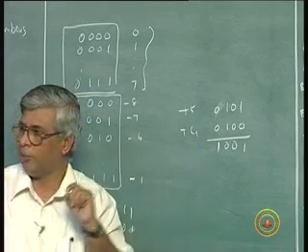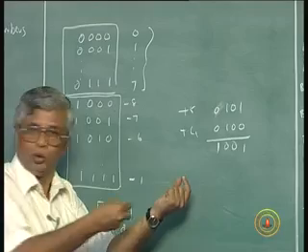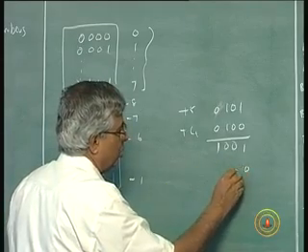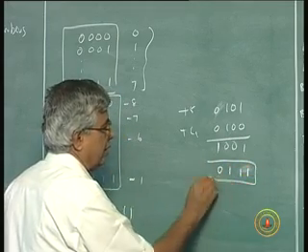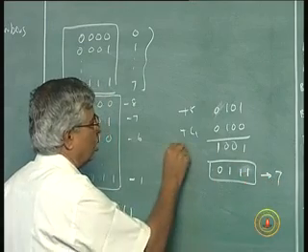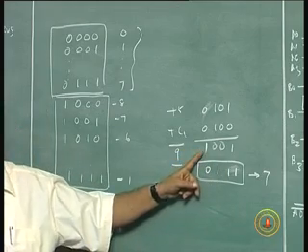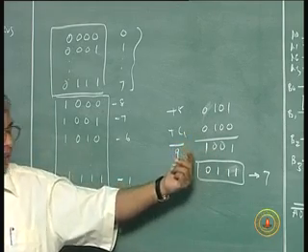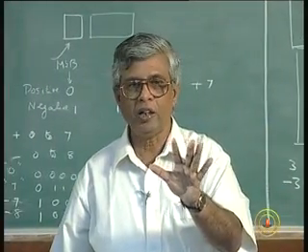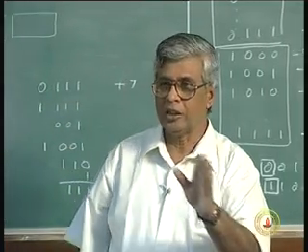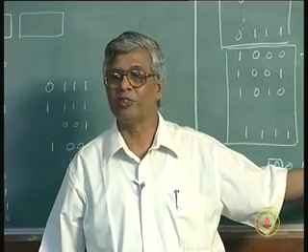Immediately I see this as a negative number because I have a 4-bit representation and the 4th bit is a sign bit. So, immediately I start taking the 2's complement of this, which will be 1 1 1 0, and this is 7, which is wrong, because obviously this should have been 9. Why is it happening? Because 9 exceeds the 3 bits allotted for the magnitude. 9 needs a 4-bit magnitude, and I have allotted only 3 bits for the magnitude representation. Since it exceeds that, it is an overflow error. Of course we will not talk about those things here, but it is called overflow.